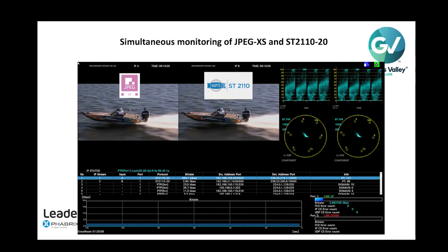Yep. And the beauty of being able to put the signals on the waveform monitor next to each other, if they started life in some other format, either SDI or 2110 and then went through a gateway to XS, or just to look at the camera. Kevin, your cameras still put out JPEG XS, and they'll still put out uncompressed signals simultaneously, and you can pull them up on the waveform monitor next to each other and look at them. I would take anybody to task to tell me which one's which. When it's only 17 lines, you can't see the difference between the two videos when they're moving or doing anything. No, with 17 lines, you will definitely not tell.